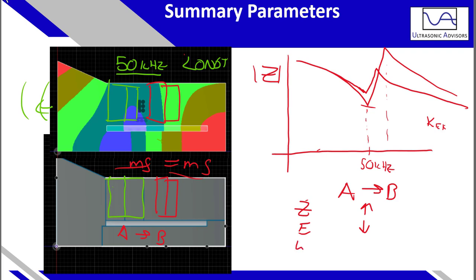Depending on your mass and stiffness, your resonant frequency could shift either way, depending on the weight and stiffness of your components. Now you have to fill this part up with steel, let's say, instead of this part. So in the way that it affects the natural resonance, that's the direction that the resonant frequency will shift. The coupling factor will decrease, and the anti-resonant frequency will definitely decrease because it's a signature of the electromechanical coupling. So that's the electromechanical coupling of that specific longitudinal resonant mode.